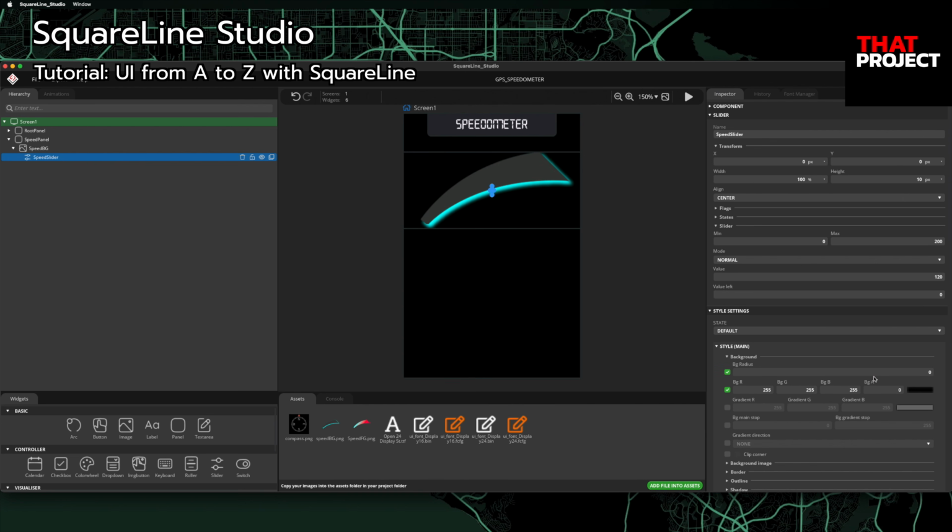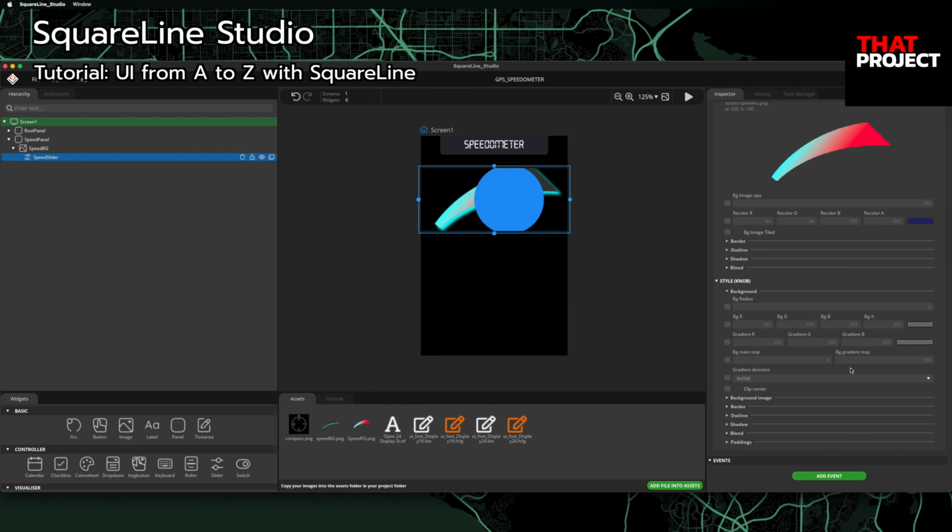Oops, nothing changes. Okay, go back to the slider size. Let's set the 320 pixel instead of 1% for its width. Also for the height, let's set it to 140 pixels like the BG image widget. Now I can see the indicator image, but the knob should be removed. The background image should be transparent.